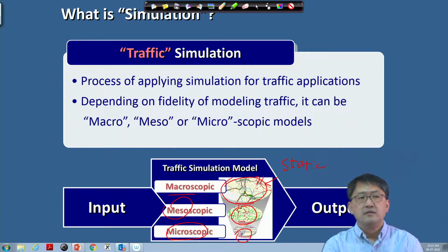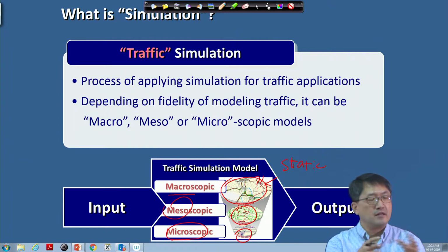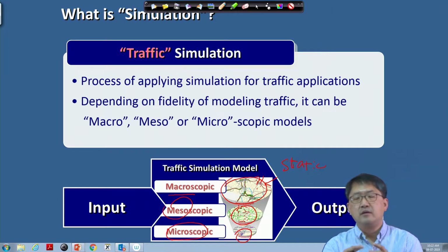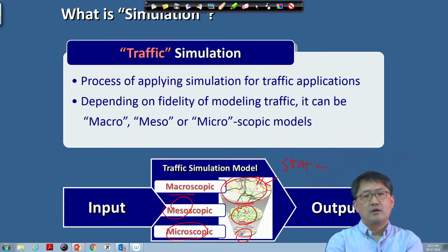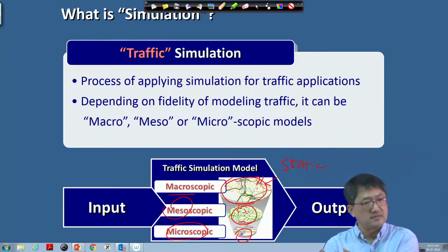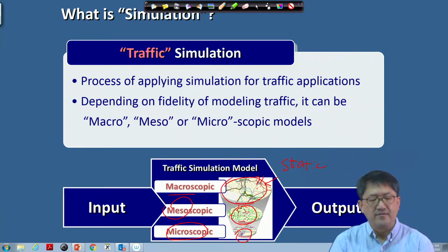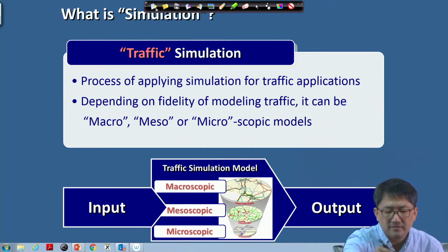But still, they don't consider lane changing in a realistic way. They do consider it a little bit, but not in the way of real individual vehicular movements, with drivers having different aggressiveness. That's another important calibration parameter. If you are calibrating for maybe Kolkata versus here, drivers in Kolkata are probably more aggressive, and you want to consider that as well. So that's how we classify traffic simulation models.